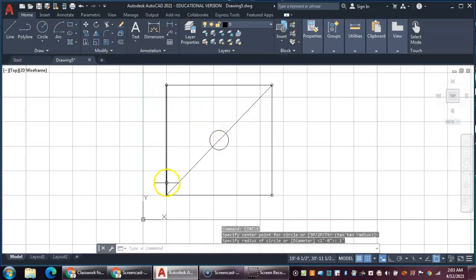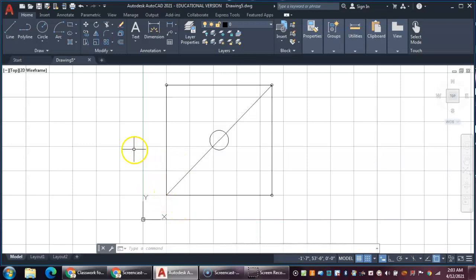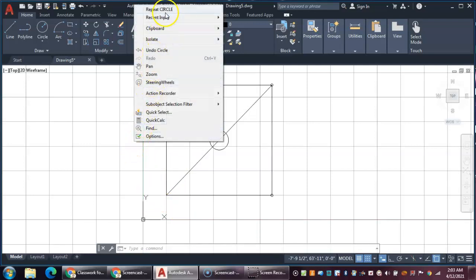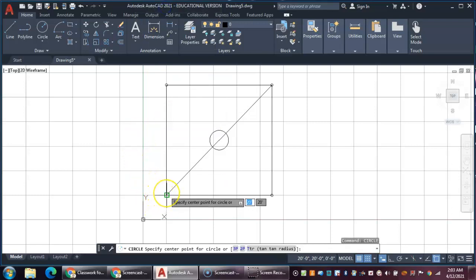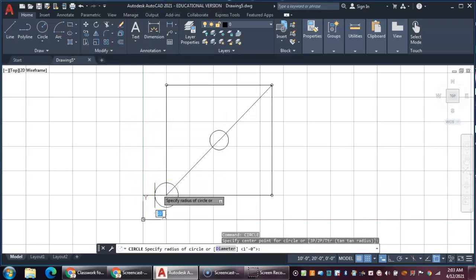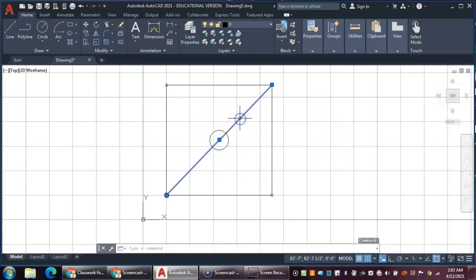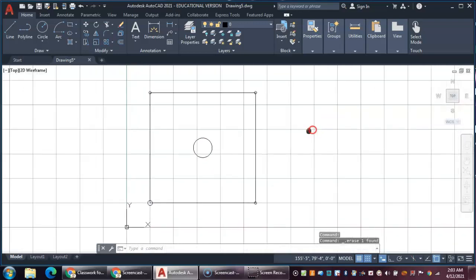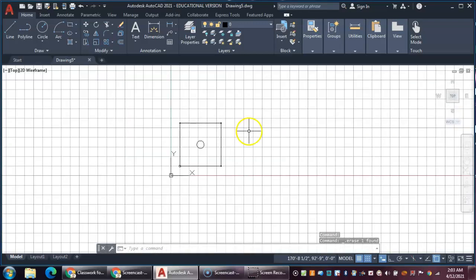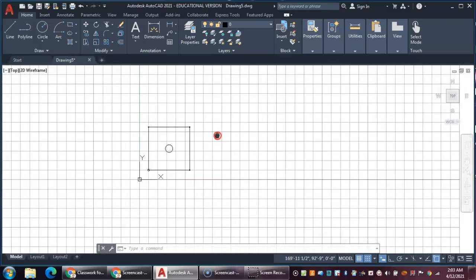and then down here at home plate, they're saying home plate is a 2 foot radius, so I'll right click, repeat the circle command, click on this, 2 foot, enter, and now I've got my bases, pitcher's mound, and the baseline. I no longer need this line, so I can delete that out of there. And now I'm going to kind of do the foul line.